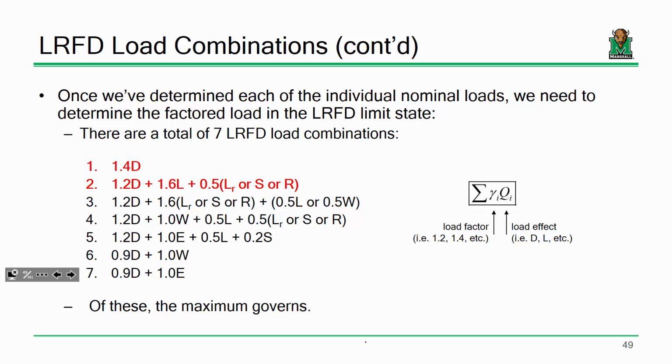Dead loads being their own self-weight, and live loads being for occupancy, what they're being used for. So let's look at that load combo as if all I had was dead loads and live loads. 1.2 times the dead plus 1.6 times the live. So why is it that the live load factor is larger? Why are we taking the live loads and multiplying them by 1.6, but taking the dead loads and only multiplying them by 1.2? Why is that?